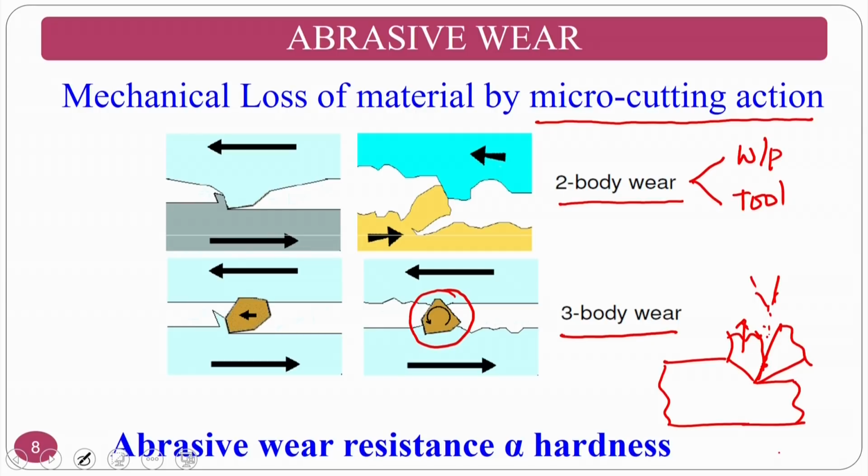So, not only the chip and tool interaction, but also foreign body particles generated by the interaction of the cutting fluid with the chip bottom side and the top side come in. Because of this, you have a chip, a tool material, and in between you have particles. Because of this, three body abrasion also comes into the picture. If I want to check this in terms of tribological aspects, for two body abrasion people normally use workpiece material and tool material and do the tribology with pin on disc and similar setups. If they want to go for three body abrasion, on the pin on disc, that is POD, instead of the disc they take an abrasive sheet, perform the experiments, and try to correlate various tribological issues. In that way this can be studied.